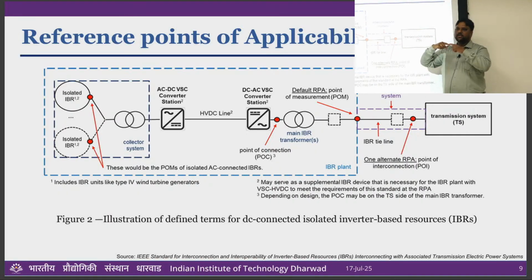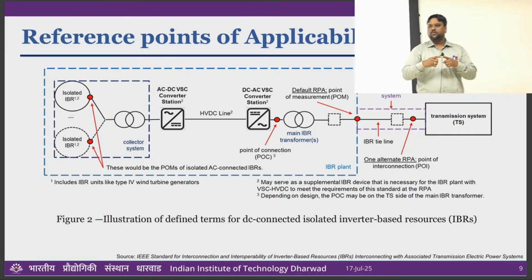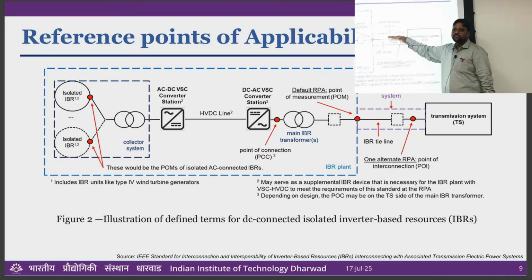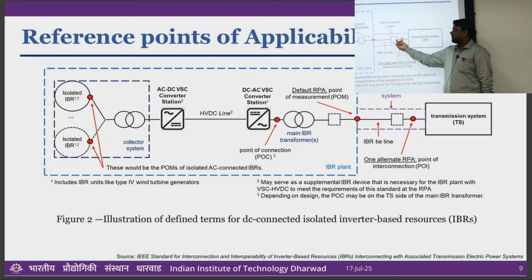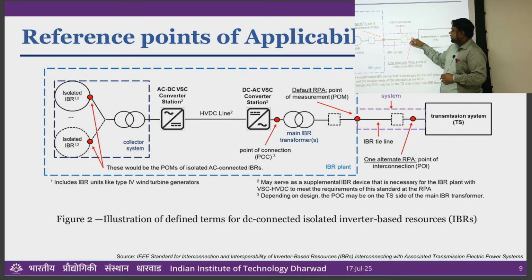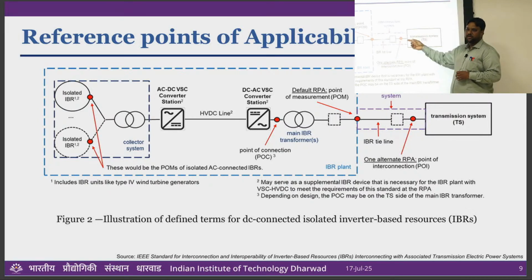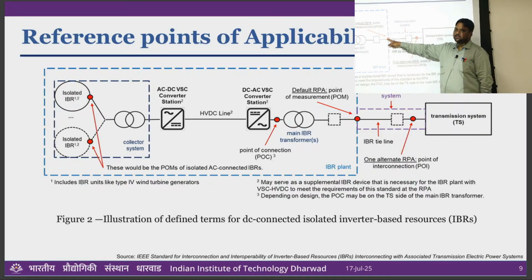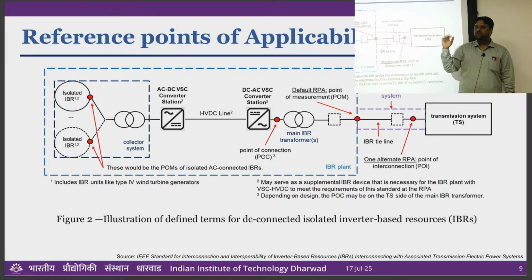So short circuit ratio is inversely proportional to your grid impedance. This is your grid impedance. Sometimes there might be very little grid impedance, so between this point and that point you don't see much voltage variation or active power variation. But if there is a significant distance from your connection point to the utility point, then you have to consider this line, and they will tell you to consider this or maybe that, which one to take. The grid people will tell you when you do the study. Okay.